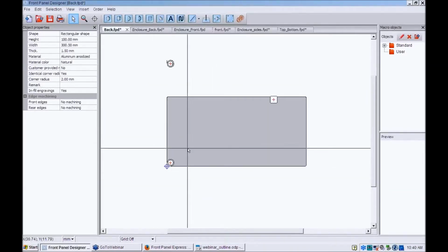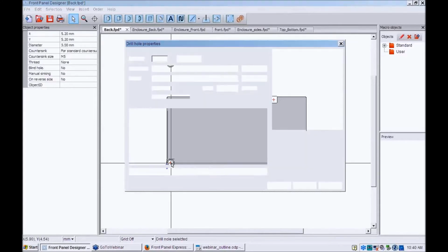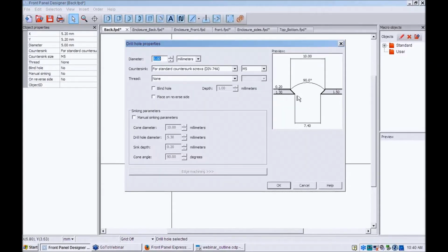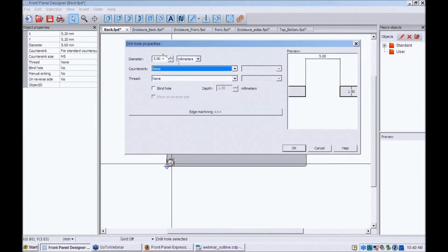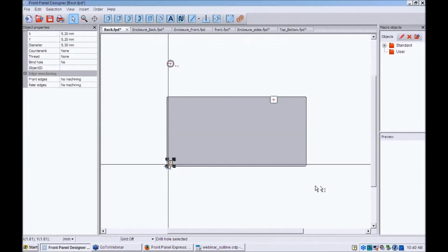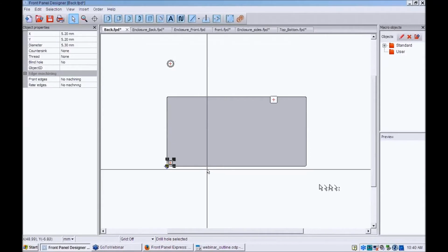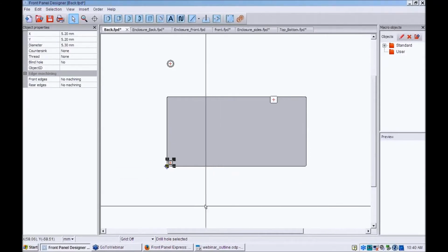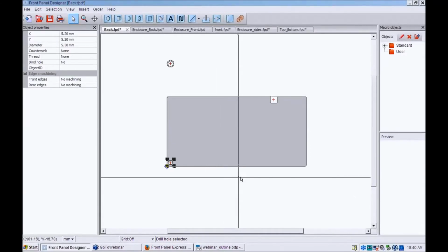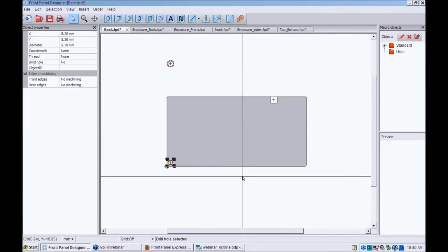And now in this case, if you select your cavity, you'll see here that the screw will actually come in contact with the profile, and this will not be a tight fit. So in this case, you would just select a standard hole and give it 0.3 for clearance of your screw, and you can just have a panhead screw hold your enclosure together. And these are also available in the types of heads you can choose from our hardware in the enclosure manual.